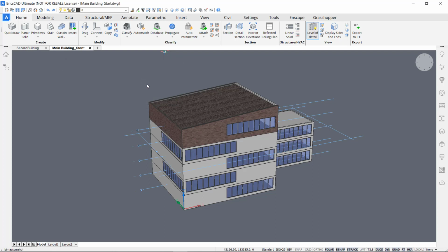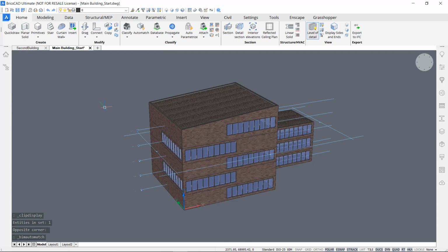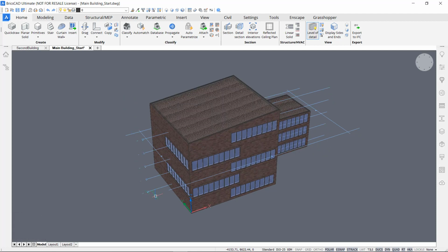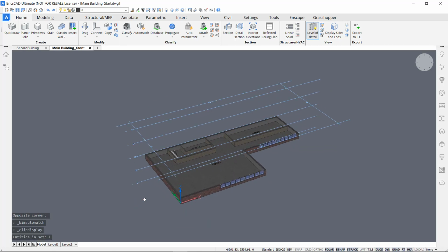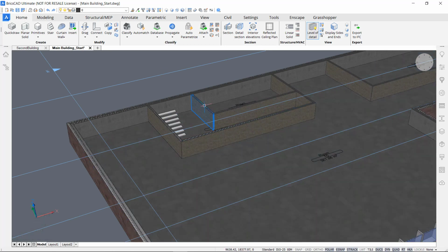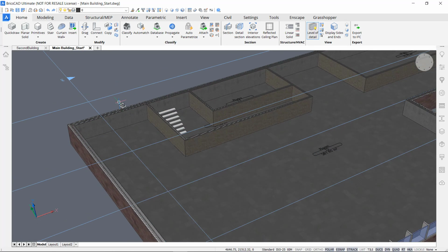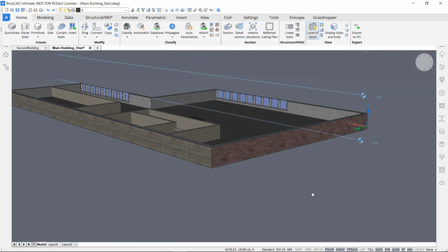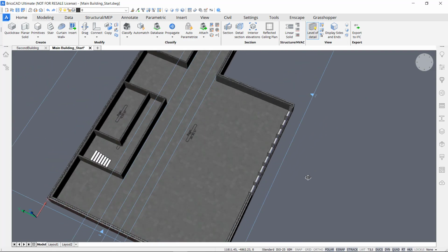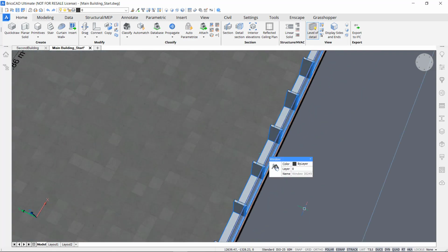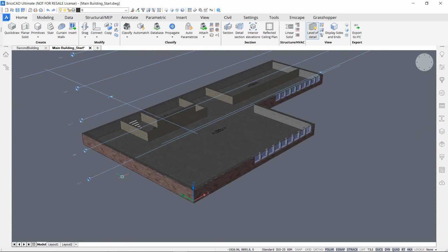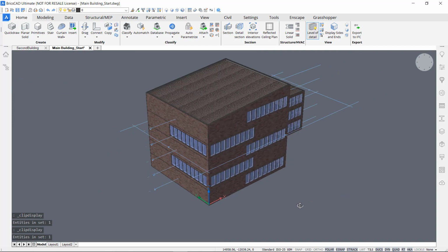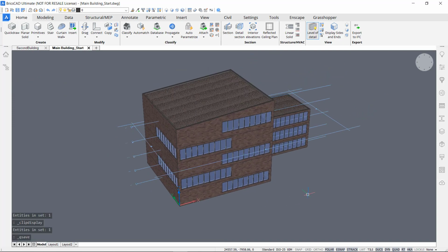So let it run BIM Automatch, and you will see it has auto-completed our entire building to the compositions and the parameters that we wanted. So let's click on another floor section and open it. And you can see here all the interior walls have the same composition. Also the back wall has a different composition from the front walls. And lastly, of course, also the window parameters, the frame depth also has been changed. So that looks good. If I close that back again and save this file, I can do the same thing for other external files.